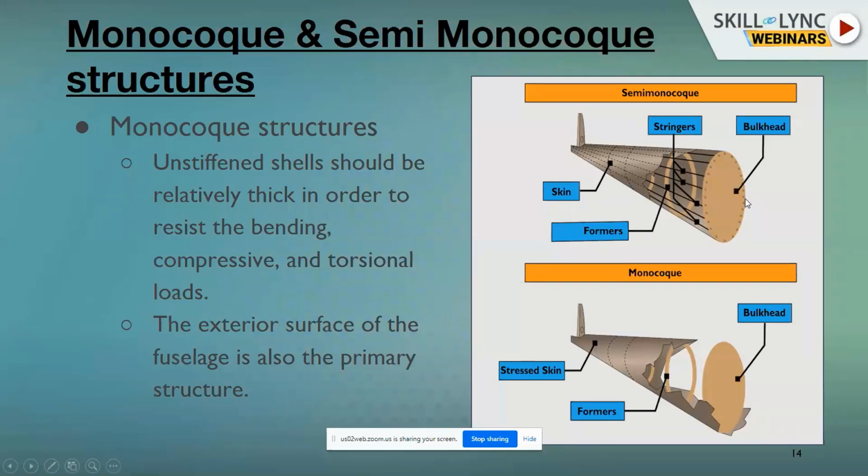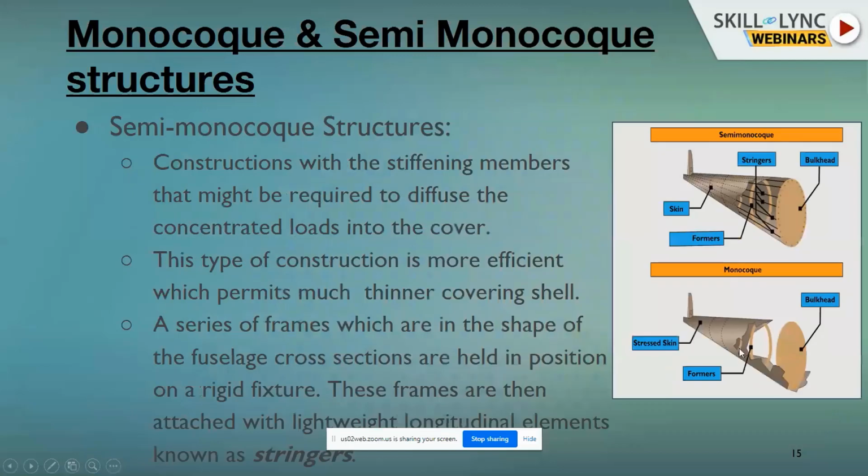And the bulkheads separate the sections. Like this is the tail section. Here you won't need any pressurization, because there is no human comfort or anything like that. So that is the drastic difference. If I want to design this structure with solid skin throughout, I can't use sheet metal. So this will be beefier, heavy, bulky, and this will be a lightweight design. That is why generally you use semi-monocoque or shell structures rather than the beefy monocoque structures. That's what I covered, most of them.